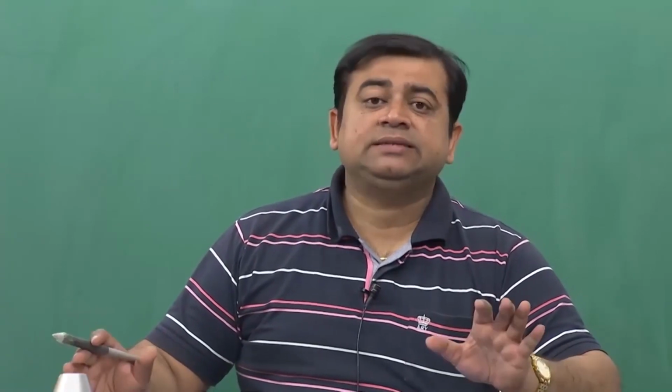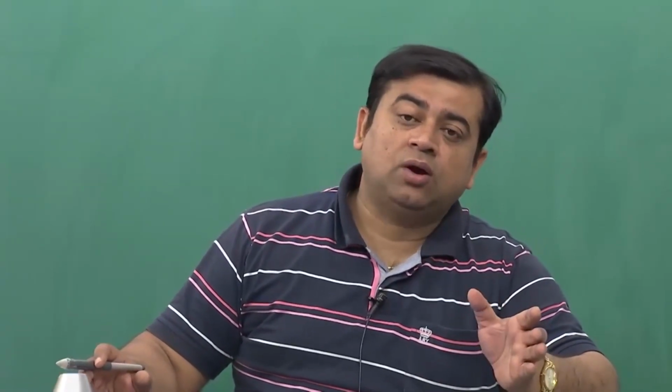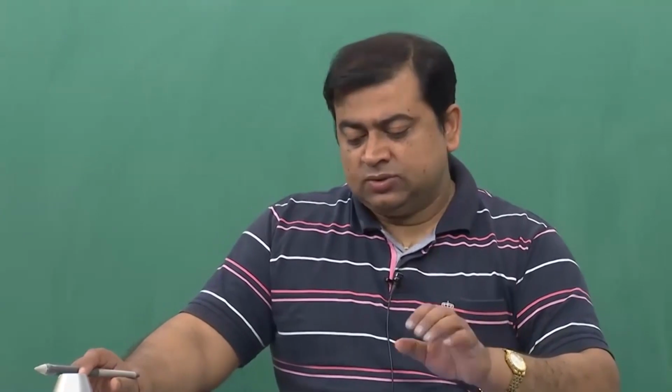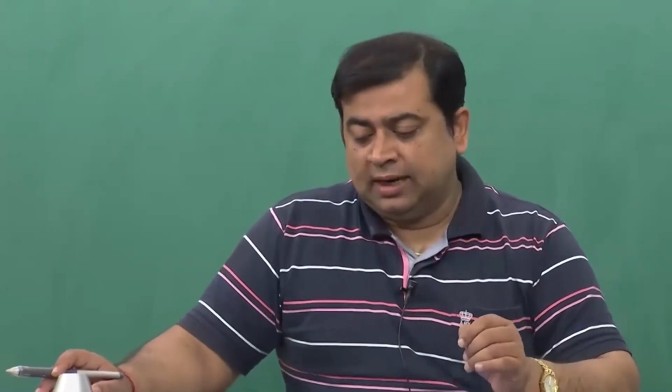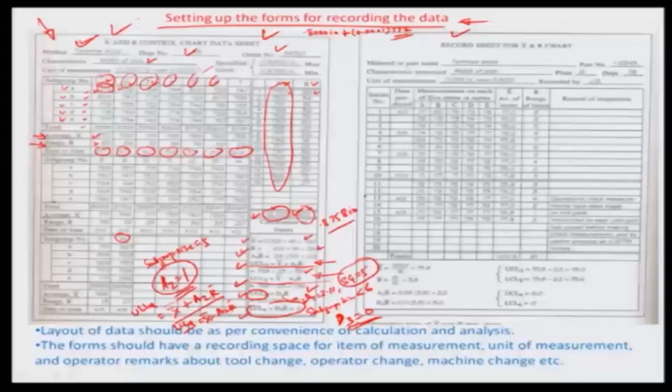So, you can have a very quick glance over a time horizon of 6 or 7 months and quickly say whether a month's production is going out of limit or not, and accordingly take a countermeasure. So, that is how you do the X bar and R control chart. I am going to show you the plot just a little bit later.